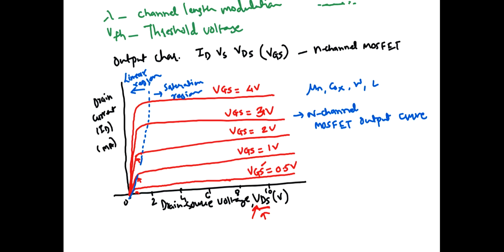That's an exercise for you. Hint is, the P-channel MOSFET will have similar characteristic curves, but the polarity is opposite. For example, the values of VDS will be negative, the values of VGS will be negative, and the drain current accordingly will be drawn.